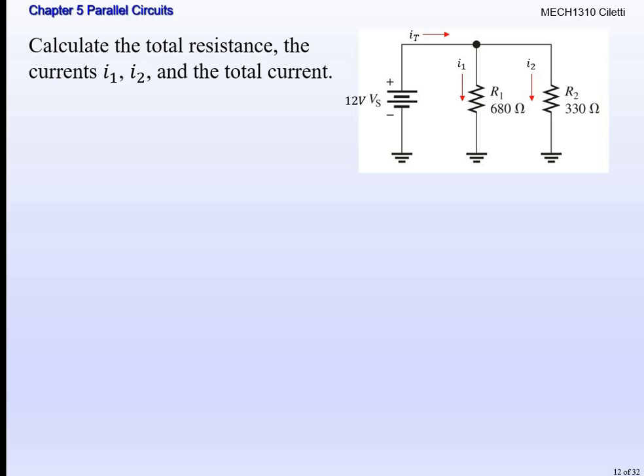This is more common in our book and from this author. Most of the time, you'll connect all those to one ground connection instead of showing them individually. But know that the ground connection means they're all going to the exact same place, so these circuits are in parallel. We're going to find I1, the current going through R1, and I2, the current going through R2. Now we're going to find IT, which is the total current, and the total resistance. If you want to pause and make sure you're getting the total resistance, that's fine. Pause, draw this circuit out so you can use it in your notes for your lecture quiz.